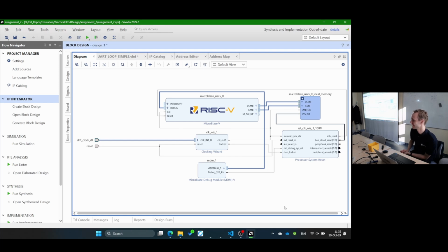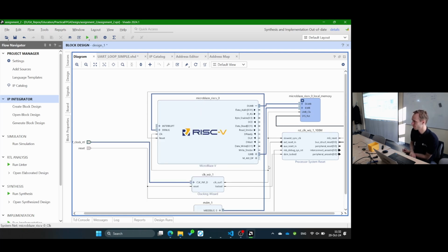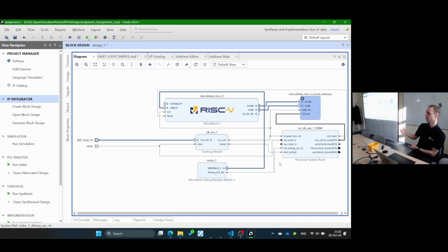What is the right approach to fix this problem? In general, I would think about how I want to connect it, and I would do the manual connection myself to figure these kinds of things out. Of course, you can also open up the port and make it a lot more, but it's a bus interface. We will come to the interconnects and those kinds of things. But modern tools understand what a bus is, and you can even write it as a bus in VHDL. And then this tool will recognize it as a bus, and that will connect all of the ports to somewhere else. And that makes it kind of nice. That's why you can automate it as well.